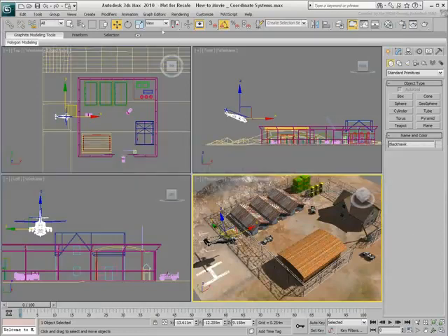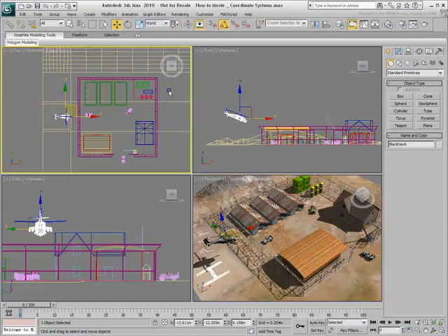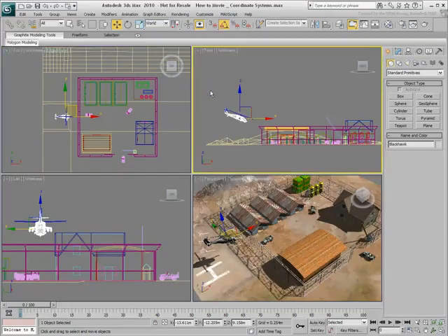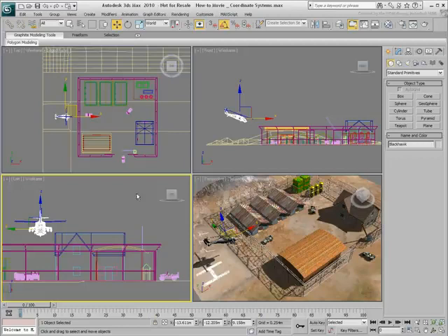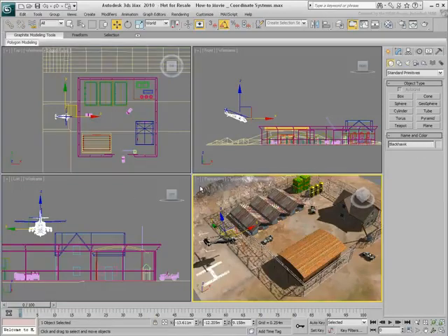When you transform objects in a scene, it's important to understand some of the more valuable coordinate systems in 3ds Max. The base coordinate system is world, where the XYZ orientations remain constant. This means no matter which viewport is active, the X, Y, and Z axes do not change, with the Z axis vertical. However, the world coordinate system in 3ds Max is not always the most productive way to work.